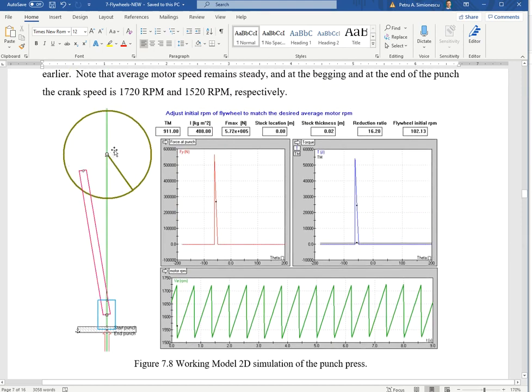you saw the disadvantage, it can be too big, but the advantage is that it protects the motor, so all the impacts and fluctuation coming from the resisting force, the punch, are not delivered up towards the motor. If there's a gear transmission, that's going to be protected by the heavy flywheel.